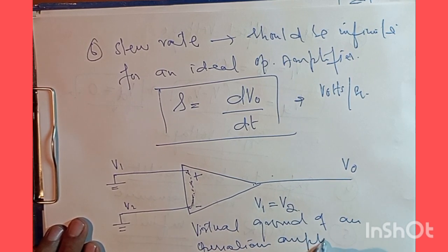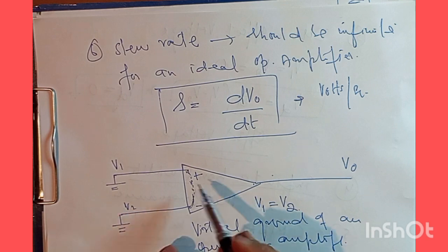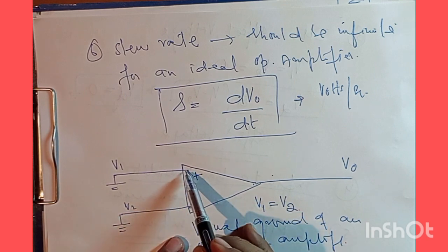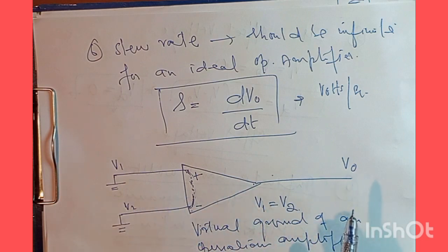So there are two important things that we have to bear in mind. That is, the input impedance of the operational amplifier is very large. So if we think of a resistance here between this and this, the current that will pass through this resistance should be practically taken equal to zero, right? And we call it virtual short.